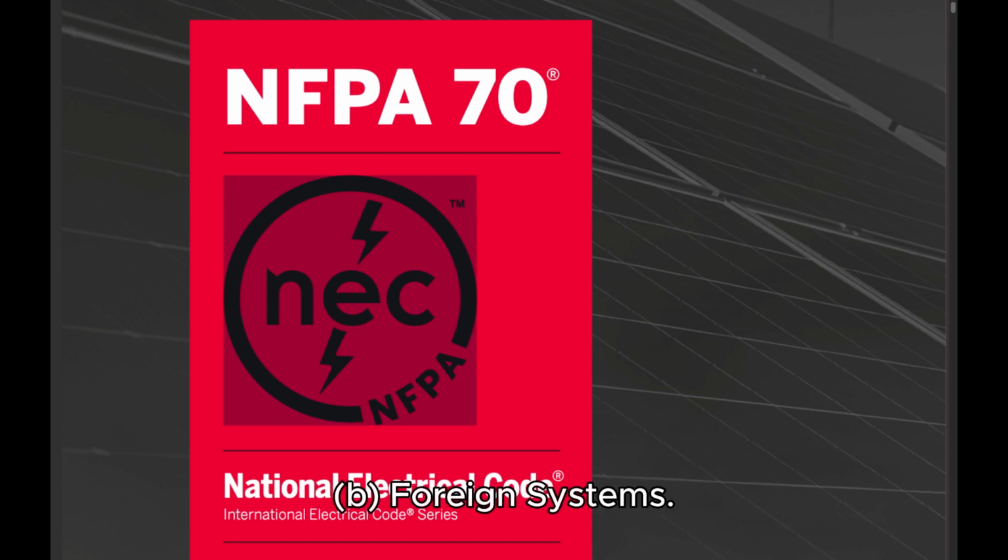B. Foreign systems. The area above the dedicated space required by 110.26(E)(1)(a) shall be permitted to contain foreign systems, provided protection is installed to avoid damage to the electrical equipment from condensation, leaks, or breaks in such foreign systems. C. Sprinkler protection. Sprinkler protection shall be permitted for the dedicated space where the piping complies with this section. D. Suspended ceilings. A dropped, suspended, or similar ceiling that does not add strength to the building structure shall not be considered a structural ceiling.